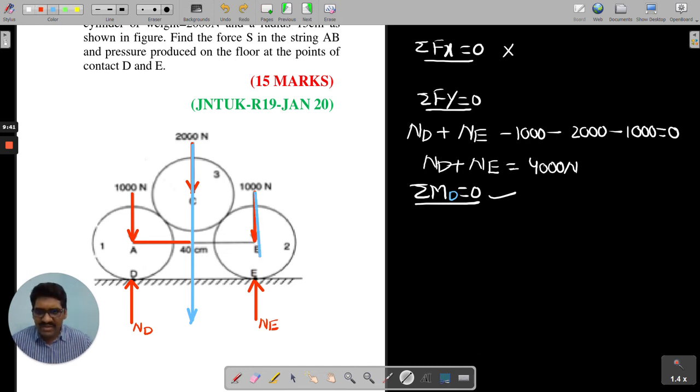Okay, this is the line of action of the force we have, all of you. Therefore I can say force into distance. How much? 40. Moving in which direction? Clockwise. That's it. What about the moment of NE? NE into distance. Moving in which direction? Anti-clockwise. Okay. Therefore, I am writing all of it clearly here.